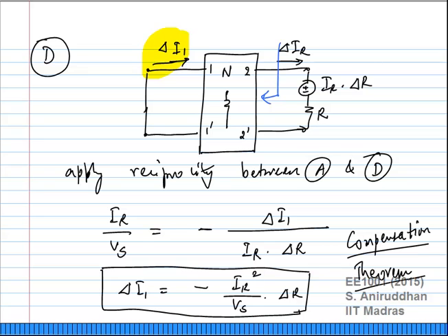Okay. So now, before we move on to the next topic, let us quickly figure out, we have seen 4 types of 2-port parameters. Suppose we want to figure out which of these 2-port parameters are suitable for a particular case. If I just have a resistive network, you can actually calculate any of these 2-port parameters. They will all be equivalent and equally applicable, right? But there may be specific cases when one or more may not be applicable. You can tie this back to the earlier case of Thevenin or Norton equivalent, right?